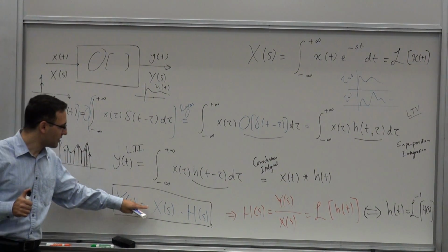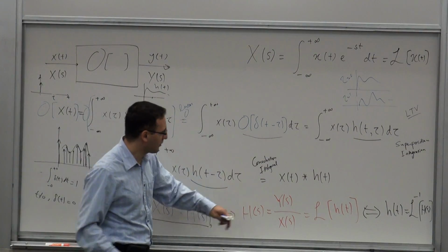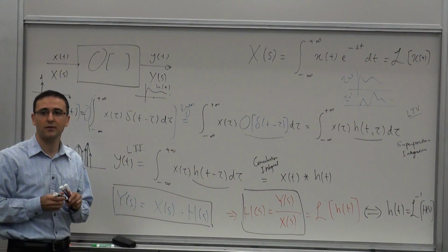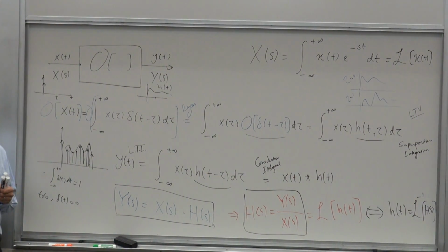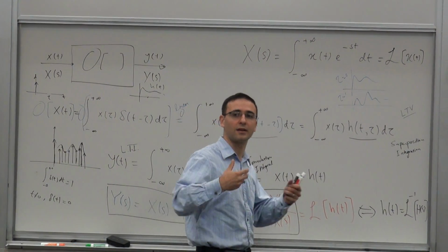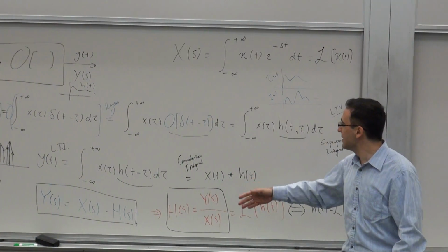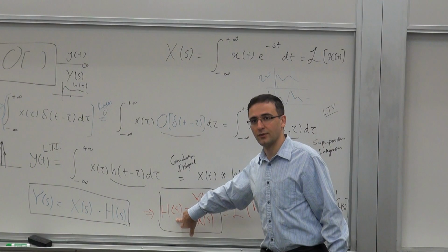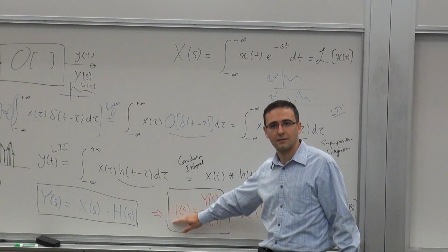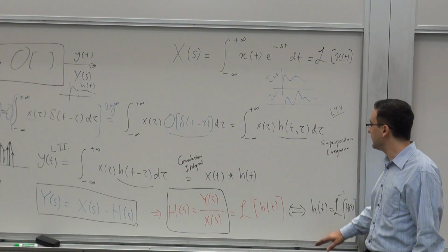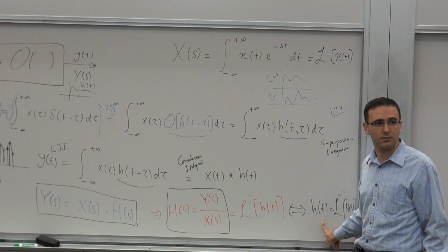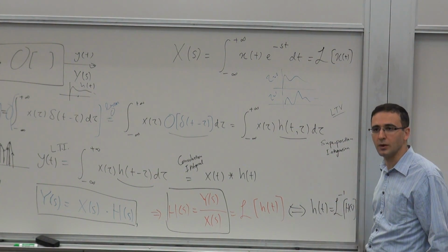But it essentially says that you can define, or another form of writing it is this. Which is the transfer function is the ratio of the output signal to the input signal in frequency. So if you use similar techniques to those we used to calculate the gain as a function of frequency, then we can determine the transfer function as a function of frequency. And of course, if s equals 0, this becomes basically the low frequency gains that we've been calculating so far. And then, if you know this, you can always calculate your impulse response and do a time domain analysis, if you will.